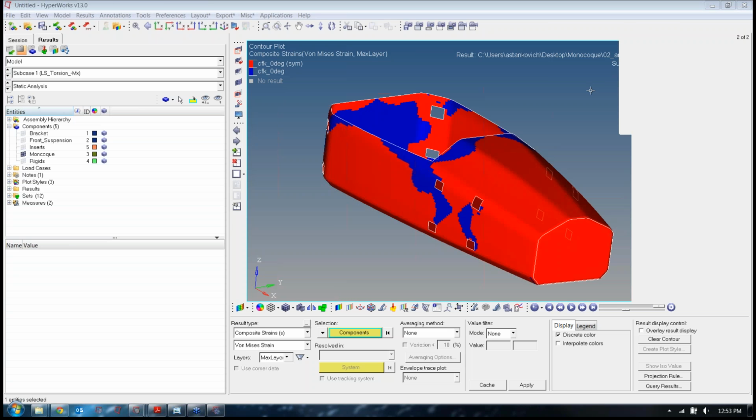Yeah, so basically what you'd do in that case is start off with a topology optimization. You'd tell it all the space that was available and the loading that it's going to see, and then run a topology optimization, which will try to tell you where the material is needed and where it isn't. From that, you'd have to go through and come up with your design.